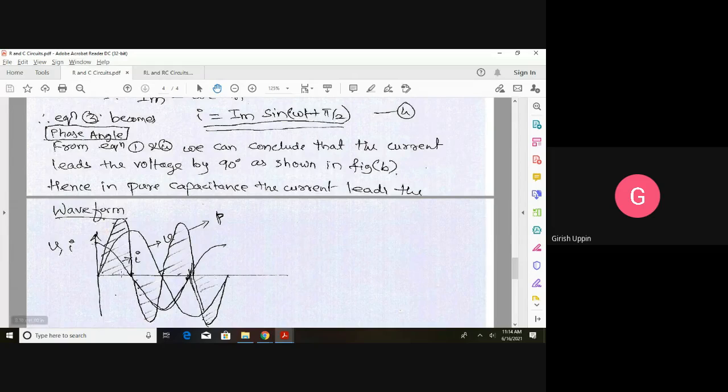So when the voltage reaches the peak value, that is when the current completely stops. At this moment, pi by 2, the current is 0. And from the peak, the voltage starts reducing. When voltage starts reducing, again the capacitance will start discharging in the opposite direction, and it will reach maximum as voltage is dropping. When voltage becomes 0, the current in the opposite direction is the maximum.